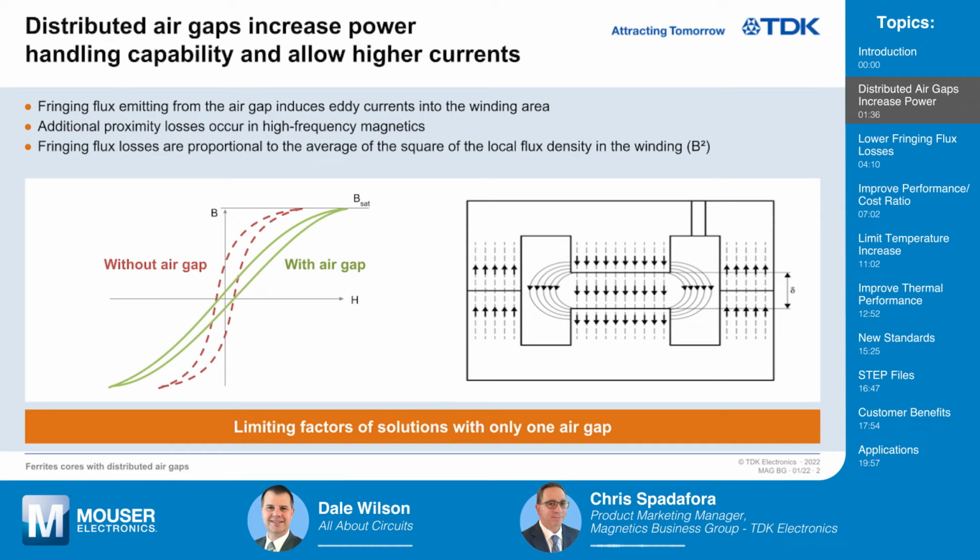So we talk about saturation. What does that really mean when we talk about a transformer or choke? Well, the magnetic properties of ferrite cores and other magnetic materials in their assembly have certain characteristics, and one of them is the saturation current level. What that says is that when the core is excited, meaning current flows through, it can handle only so much.